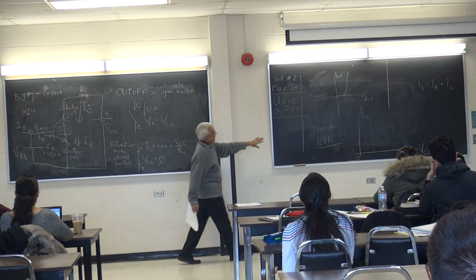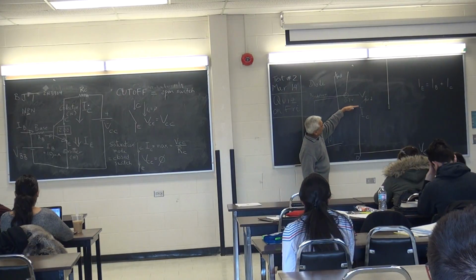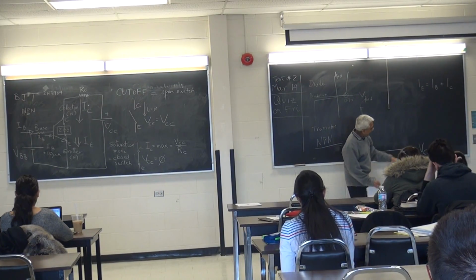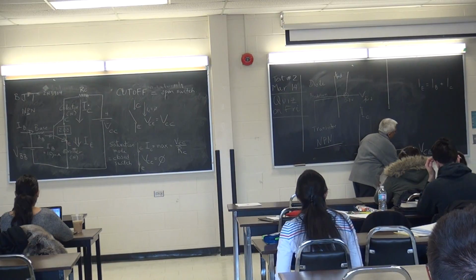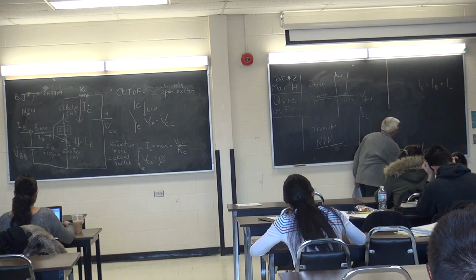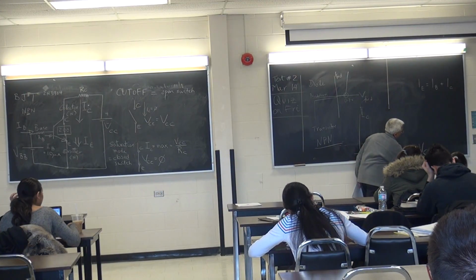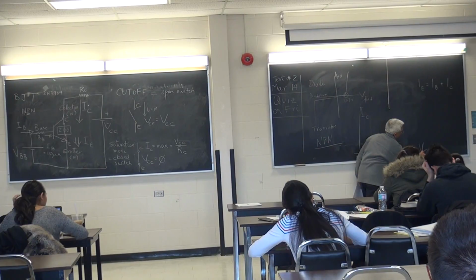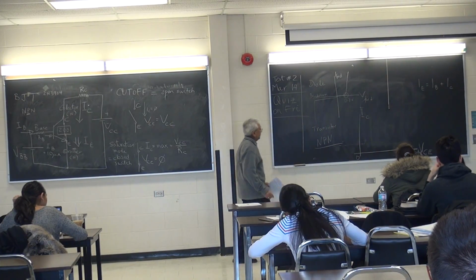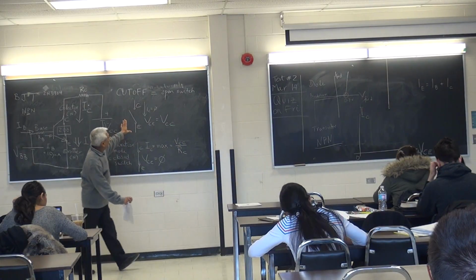So what I do is I show a current of 0. Where is the current of 0? Down here. So at that point, my voltage collector to emitter is VCC, the supply voltage on the collector. So I call this the cutoff point. That's cutoff. Okay? So that's 1 point. That's when the transistor is fully open.